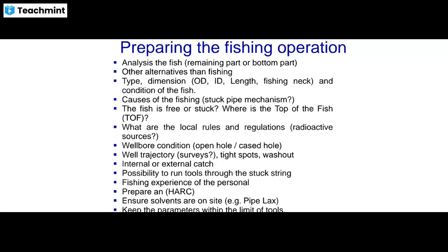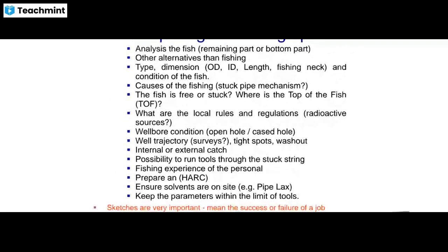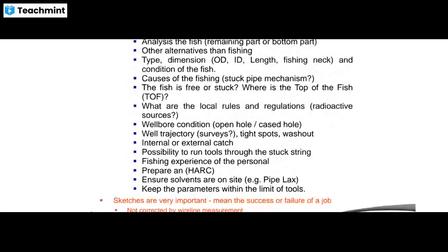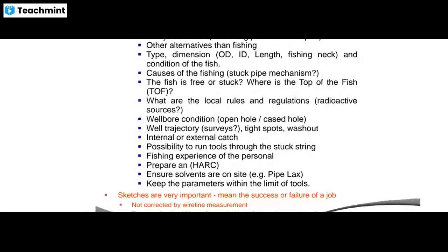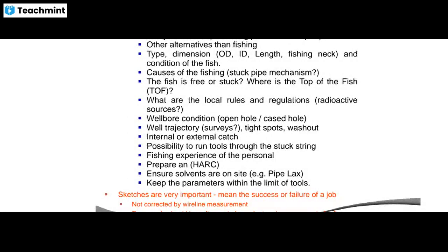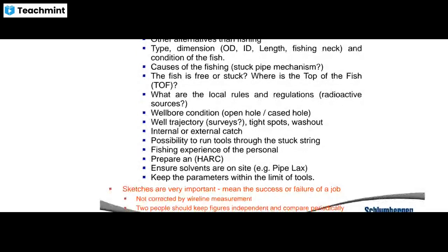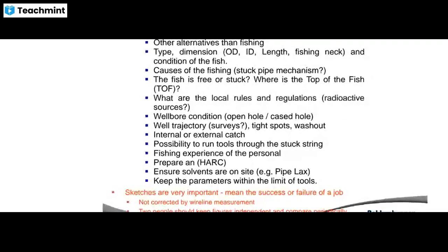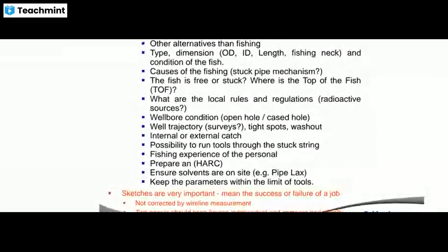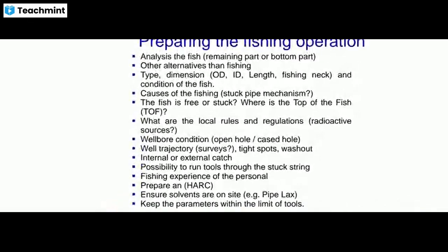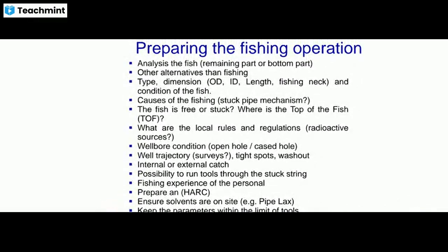or internal or external catching, possibility to run tools through the stuck string, fishing experience of the personnel, prepare a HAZOP, ensure solvents on the site, and keep the parameters within the limits of the tools. Then sketches are very important, meaning the success or failure of a job, then corrected by a wireline measurement. So two people should keep the figures and compare them periodically. So this is your preparing the fishing operations.